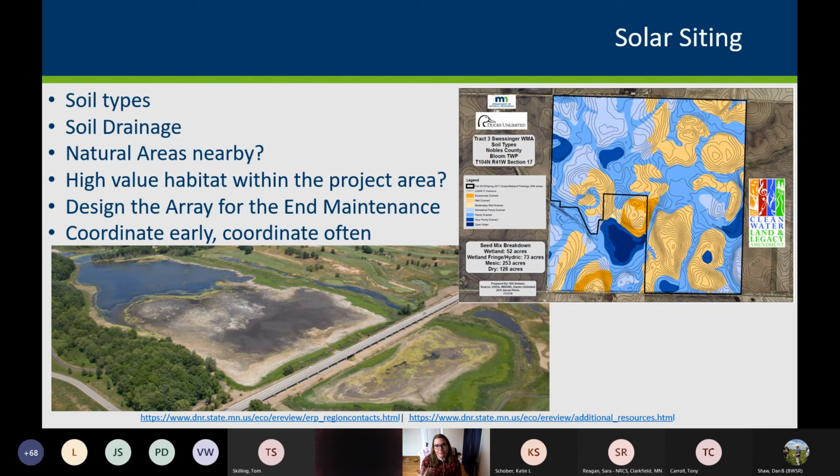And so sometimes there may be like 5 sites that they can choose from that make sense based on where the current infrastructure is. What we see and what we want to avoid is siting these in wetlands, because it just leads to all kinds of problems. Solar panels sink, solar panels get highly invaded by invasive species. There's all kinds of vegetation management and establishment issues, which means there are issues with site permits. It just becomes kind of a mess.